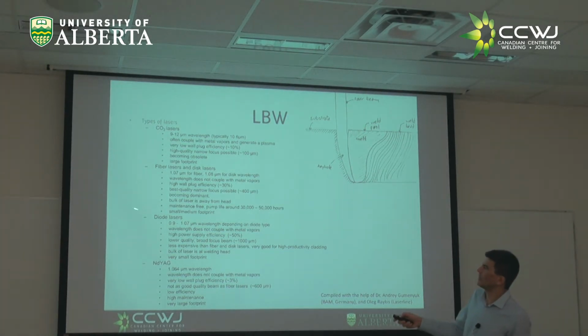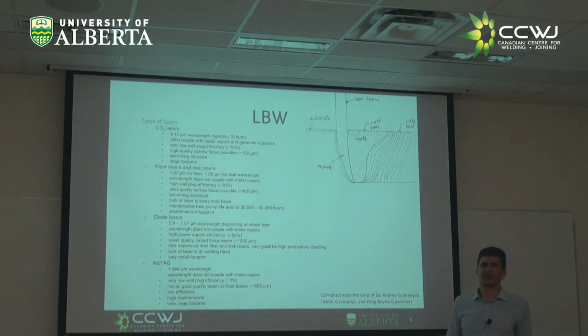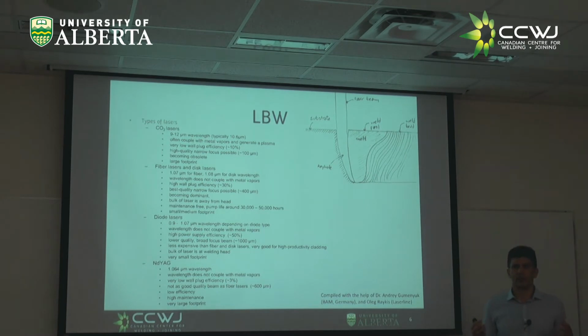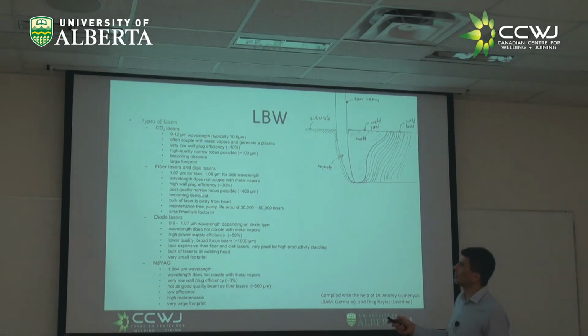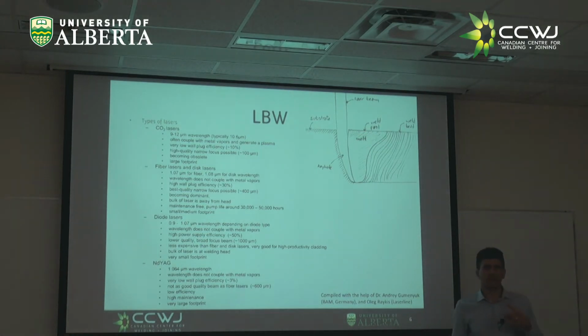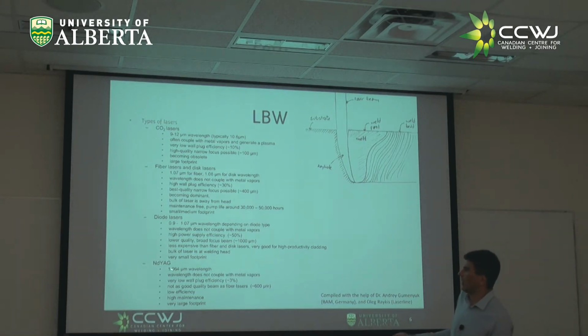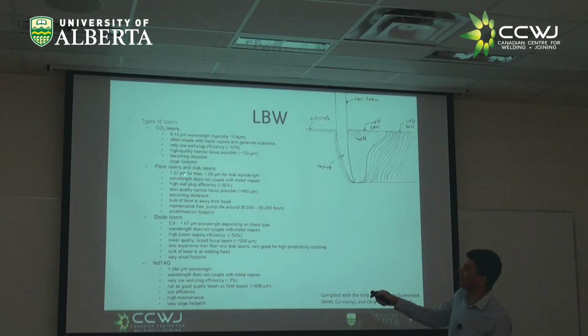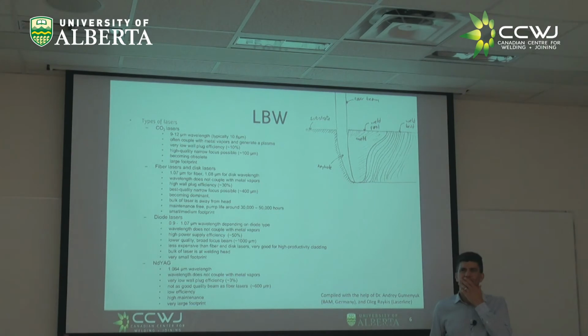Can be a diode laser or a fiber laser that is to some extent very different, but to some extent very similar, right? They are semiconductors, like very, very powerful semiconductors. So let me tell you about these things. The first thing to pay attention to is the wavelength of the light. Look, neodymium 1 micron, diode laser 1 micron, fiber laser 1 micron, CO2, let's call it 10 microns.